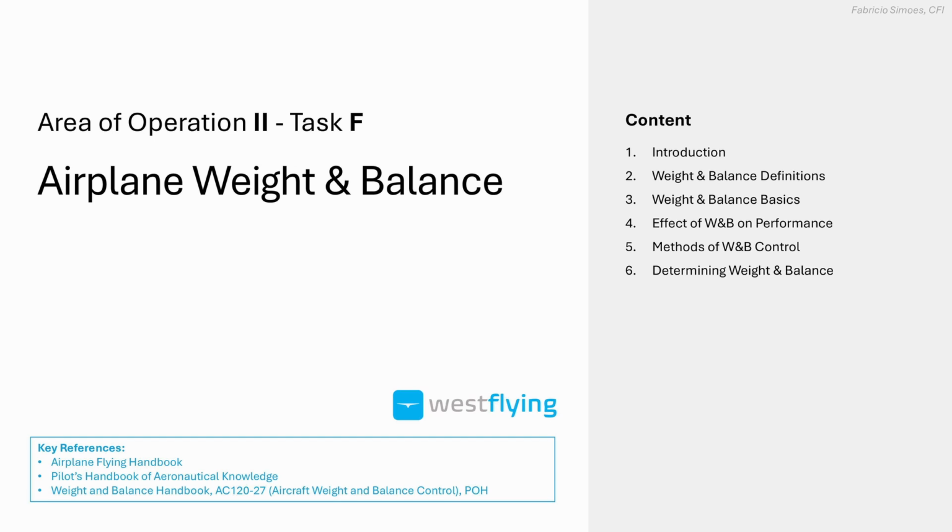As a pilot in command, it is your responsibility to ensure that the aircraft is within the allowed weight limit and CG before each flight. That impacts how many passengers you will be able to carry, how much fuel, how far you will be able to go, how much baggage to allow into the airplane, and sometimes even where your passengers should be seated.